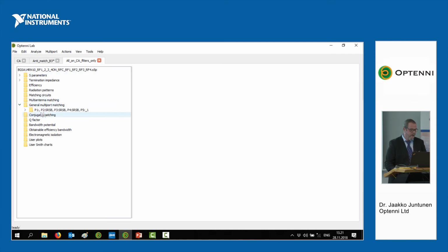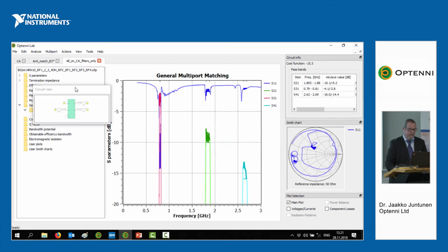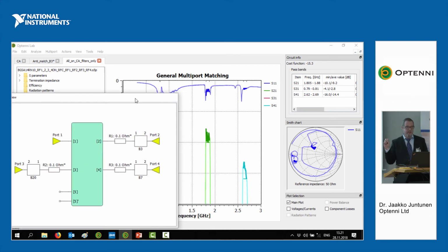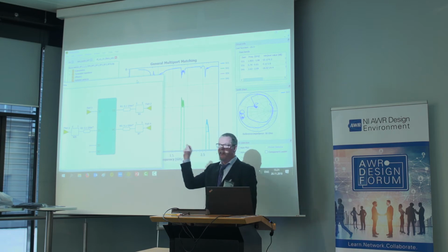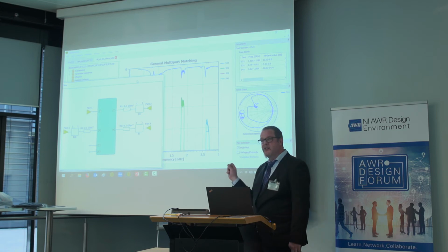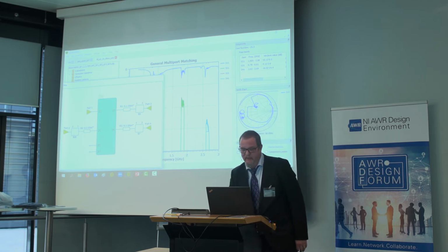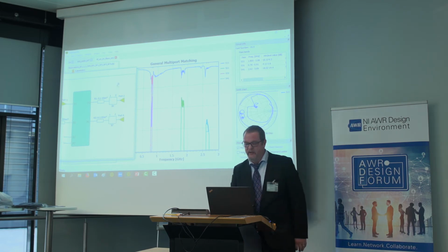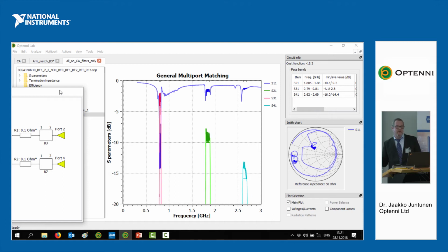Here, this green box in the middle is the switch, with the state of all branches on. And I have put in some small resistors so that I can dynamically switch each branch on and off. But if we have, let's say, the filters connected here, especially for band 7, this is the insertion loss. Band 20 looks good, more or less. Band 3 looks medium, and band 7 looks bad. So it's minus 15 dB insertion loss. And the main reason is perhaps that it's so severely mismatched.